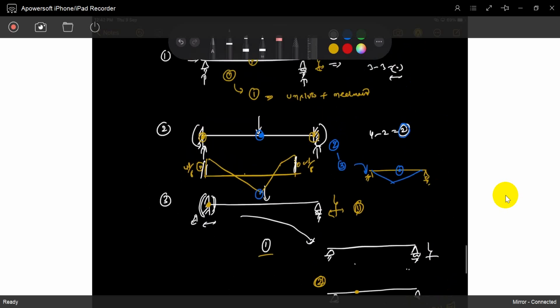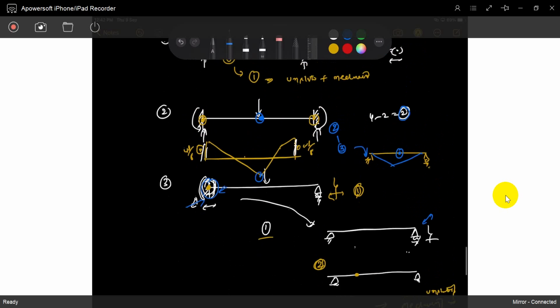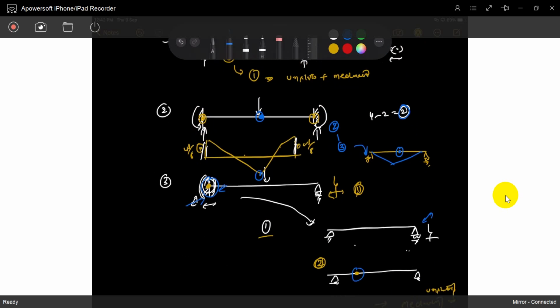If a plastic hinge is formed at a location, there is no problem for the structure. The structure is still taking the load. It is a stable structure. Only when hinges form at further locations is the structure collapsed. That is called the collapse system or ultimate load carrying capacity. It's the ultimate final, like a collapse situation. Okay, got the idea?